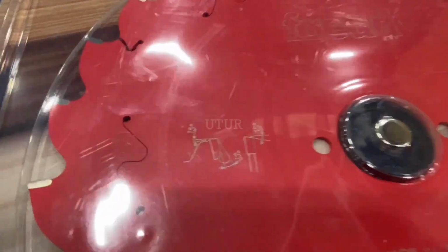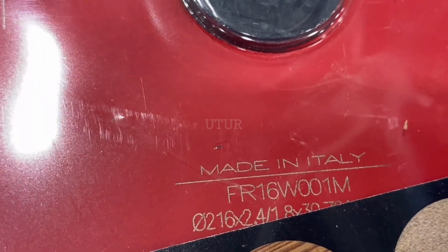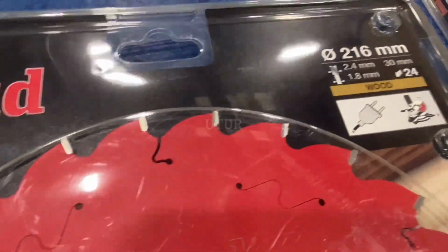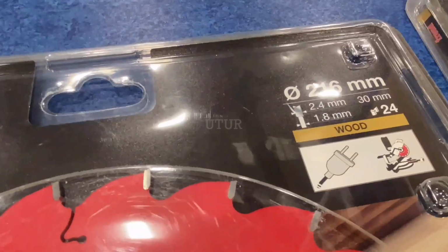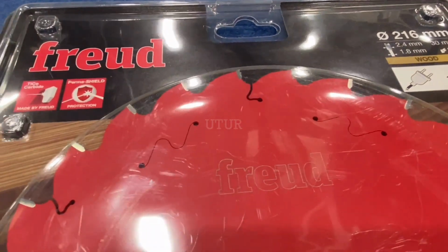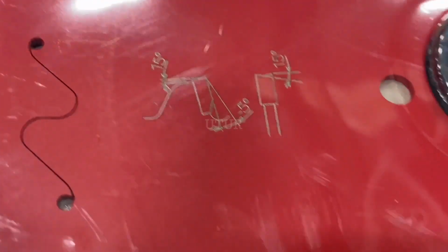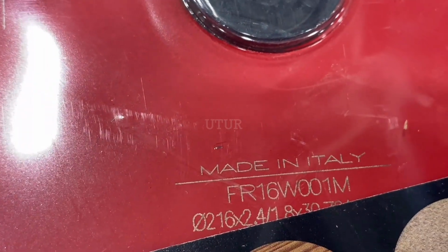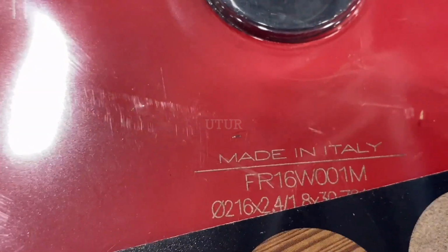But if the blade type was a flat top grind with a tooth angle bevel configuration of 0 degrees, then it would have been more suited to say that this was a designated ripping blade, which would enable fast ripping and rough cross-cutting, but this is not the case, okay? This is a general purpose blade with an alternate top bevel tooth angle configuration of 15 degrees, which can be used for ripping and cross-cutting.